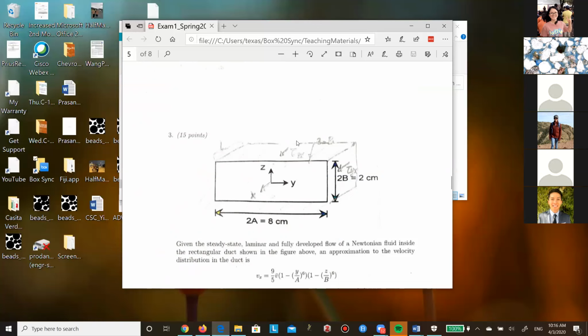And since the Z equal to B plane is at the higher value, tau Zx gives me precisely what I need, and that is the viscous force exerted by the fluid onto the solid. On the bottom plane, technically what tau Zx is giving me is what the solid is exerting on the fluid, so I just have to take a negative of that.